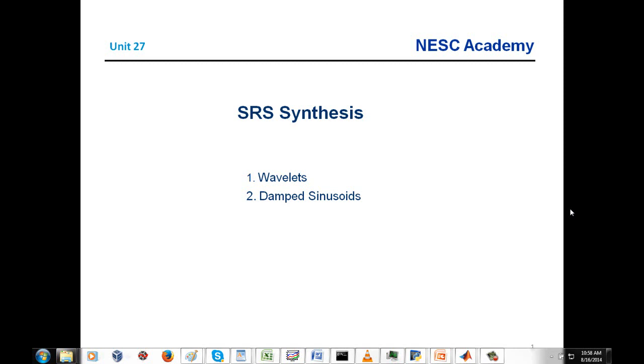There's actually another type of shock and vibration test. It's called time waveform replication, and that's a case where the idea is to actually replicate the field shock or vibration time history in the test lab. But let's save that for a future webinar. So today we're going to just assume that we can take our SRS spec and come up with any type of reasonable waveform we can to satisfy it.